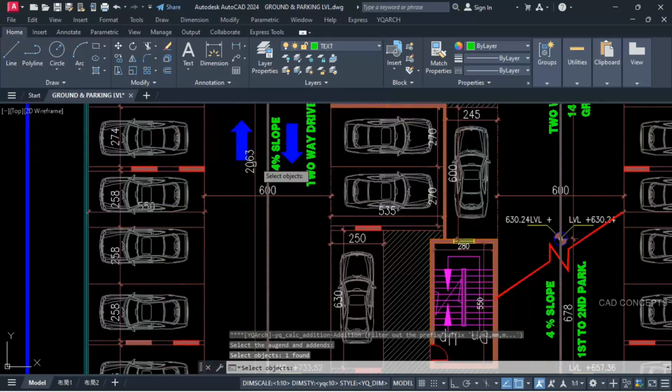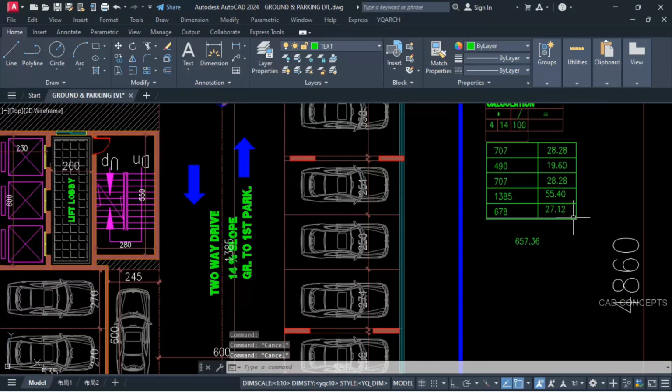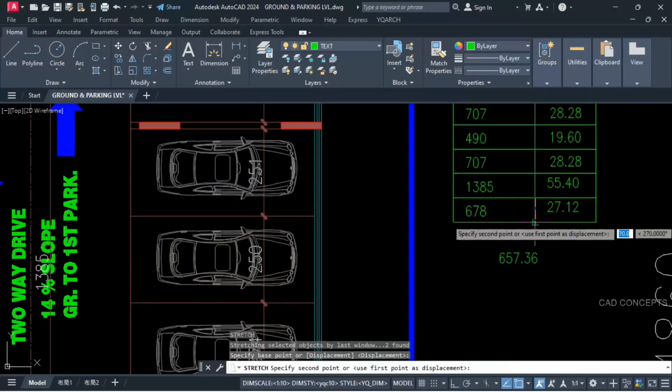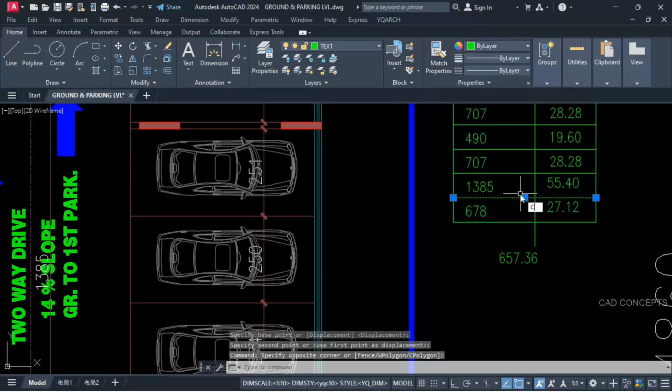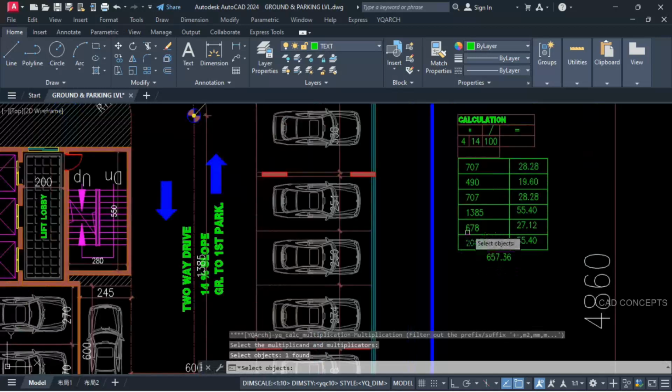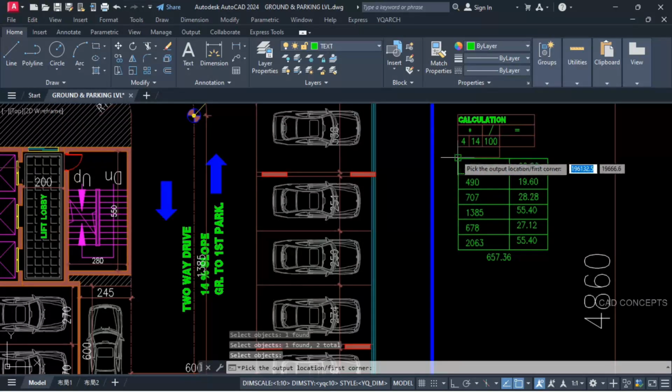So let this value, we don't have pre-calculation for this 2063. 2063 how much 4% we have to calculate, okay. Then simply we will place in next level. So this is our 2063, okay. So first we have to calculate 2063 value how much for 4% slab, okay. Let this multiplication, select your this value into 4, then by 100. It means 82.52 will add your next height for your 4% slab, okay. Double ST command, select this to this match here, okay.